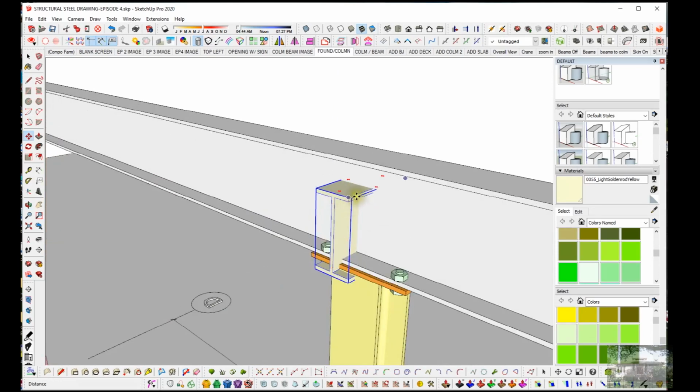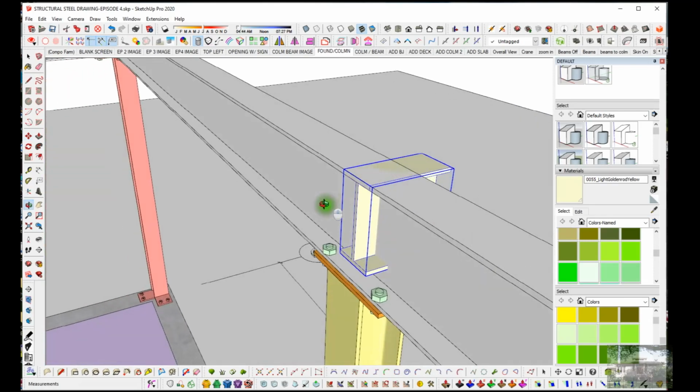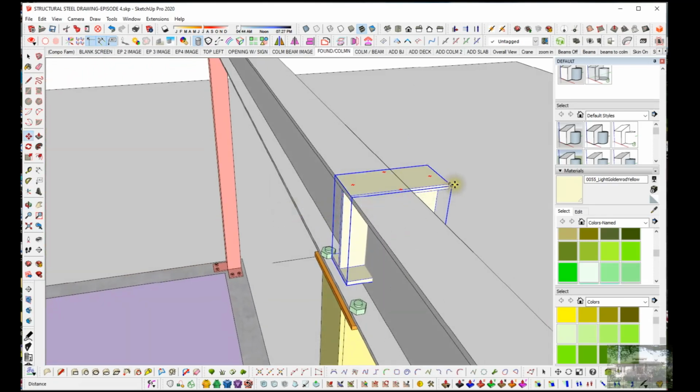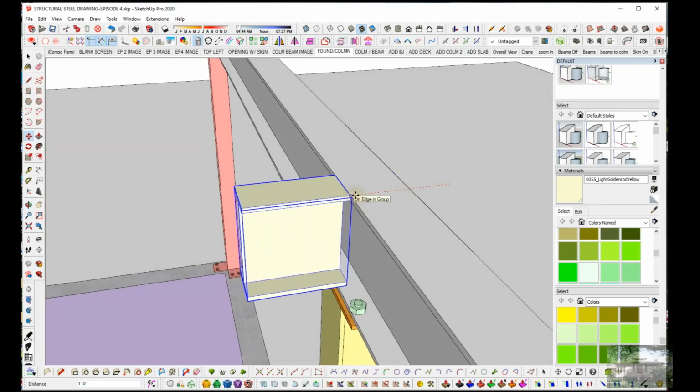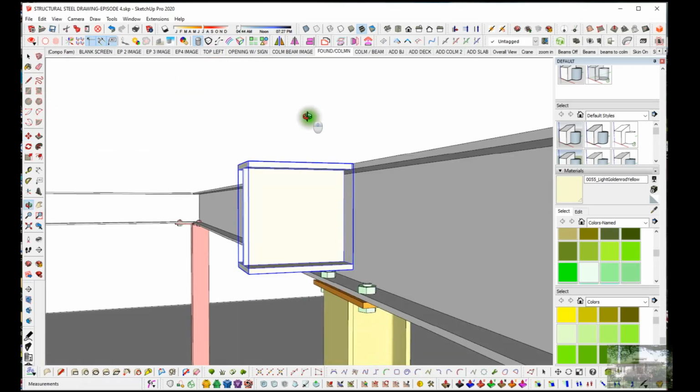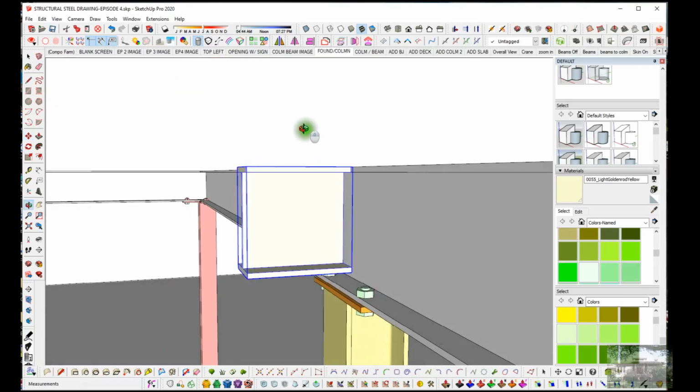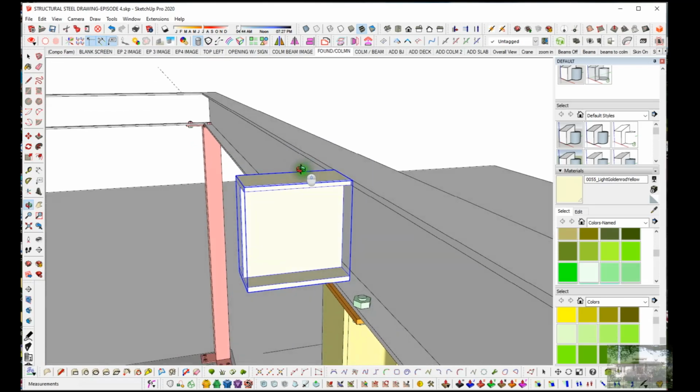So we've got to put this up on this beam here. Beam steel is all erected by top of steel matching. So that's what I'm doing. The beams are different sizes, but you want the tops to match because that's where everything bears.